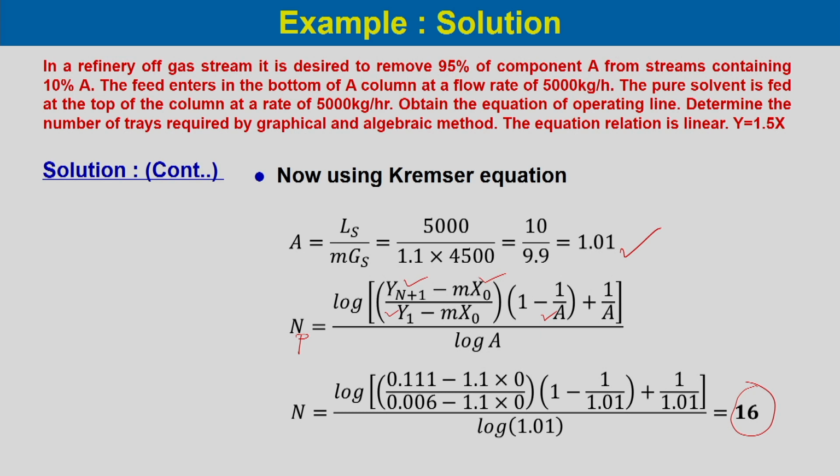So, using the Kremser equation, we can simply calculate the number of stages required for a particular problem, but we have to be very cautious about the concentration of the solutes which is transferred and how far it is valid to use the Kremser equation. If the solute transfer is appreciable, we should not use the Kremser equation; it gives only a rough estimate if you use it in case of change of concentration and change of molar flow rate of the gas and liquid.